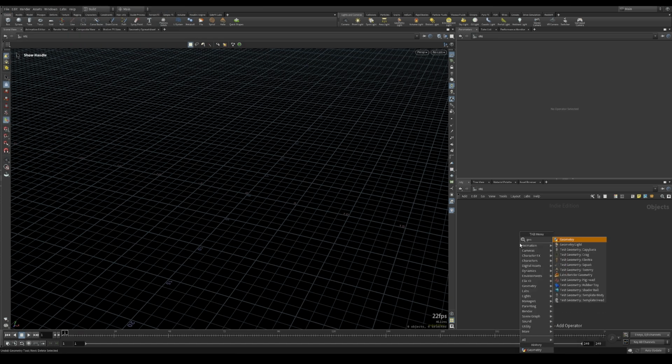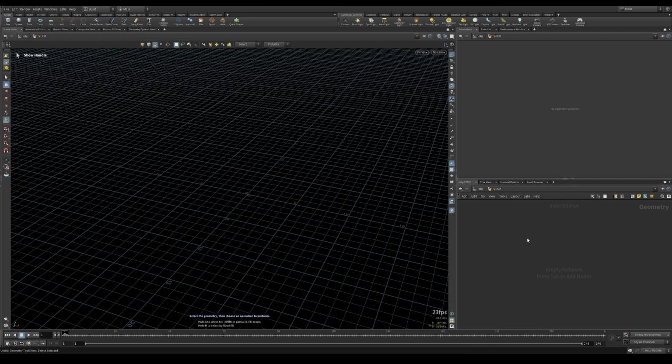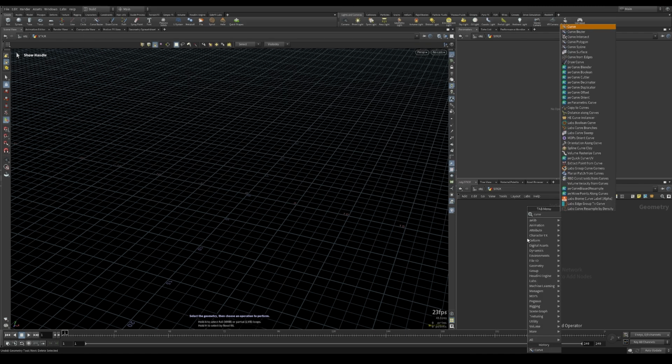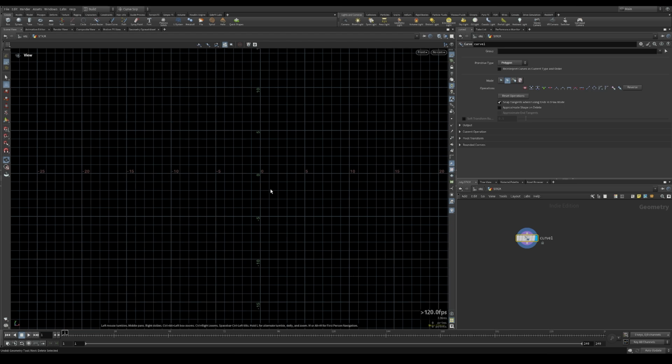Let's drop down a geometry node. We will call this stick, and this will hold everything about our stick mesh and animation. So dive inside, and we want to drop down a curve node. We will draw only 1/4 of the stick and then mirror it. So we want to go in the front view with the space and 3, and let's draw our stick.